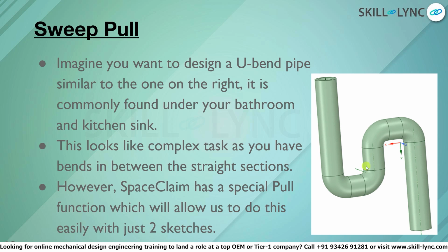You need to define around 4 axes, 1 axis per each revolve pull motion. And it gets very complicated and complex in addition to designing all of the other straight portions or straight sections. So that is in no way a common way to do such a task. SpaceClaim offers us a special pull function which will allow us to do this just with 2 sketches.